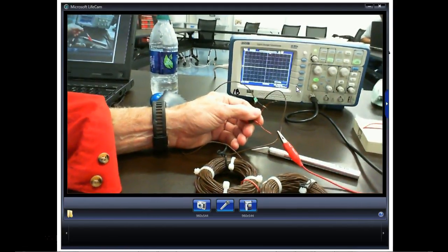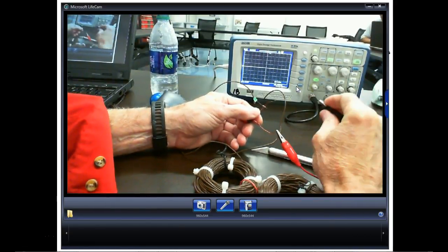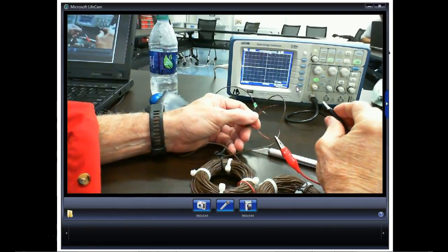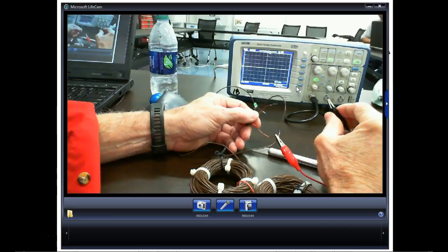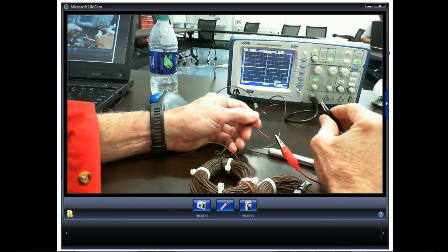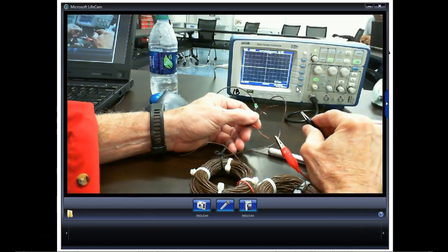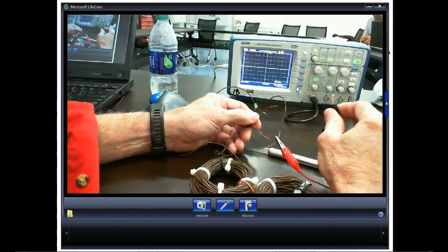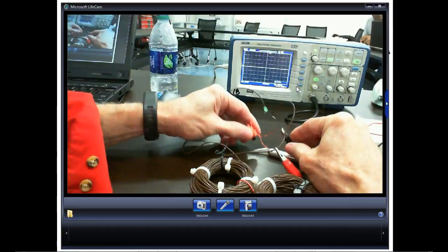We used to call them AC generators and DC generators, but the problem we had is when the cars first came out, they had DC generators on them, and everybody called them generators. So when they went to the alternator, because it was more efficient, they didn't want to call it AC generator because people would get the term generator confused. So they started calling it an alternator. But in the electrical field, you have AC generators and you have DC generators. You don't have alternators.